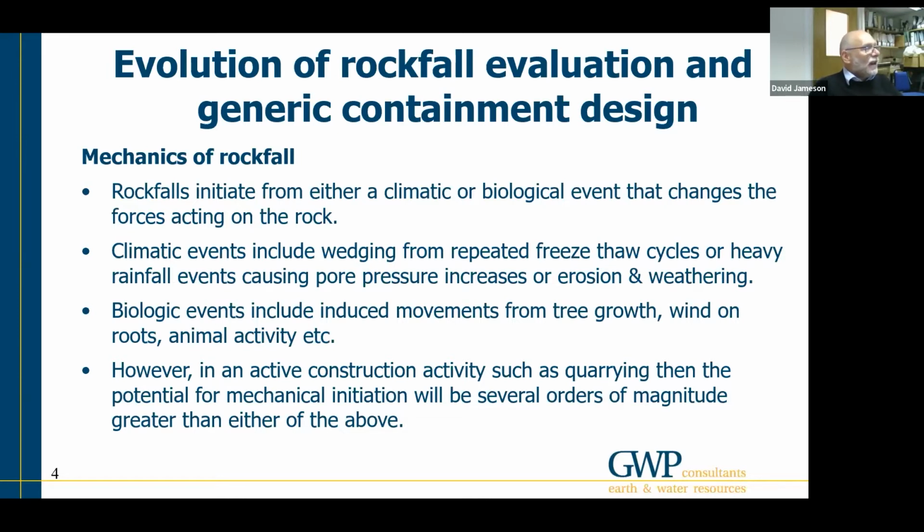But all of those are fairly low energy activities, and when you're in a much higher energy activity, such as construction, excavating faces and or blasting faces, which results in the blocks on the face being fragmented in any case, and then excavating those faces, leaving loose rock on the faces, you have a potential for mechanical initiation, which are several orders of magnitude greater than either of the other climatic or biologic events that I've talked about above. So we need to consider how we're going to constrain or contain any rockfall from faces.